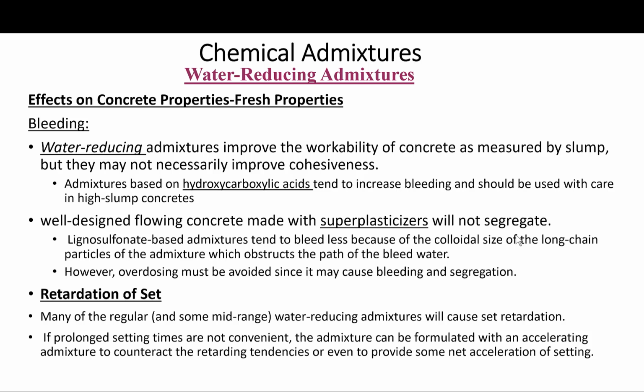Okay, so on the other hand, superplasticizers have air detraining properties, and an air entraining agent must be added to the concrete to get a stable air void system before a superplasticizer is added. Okay, so again, testing, verification of the interaction between the admixtures, and understanding basically the literature, the documents that come from the manufacturer as to the interaction between the various admixtures.